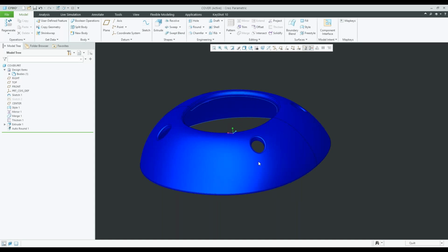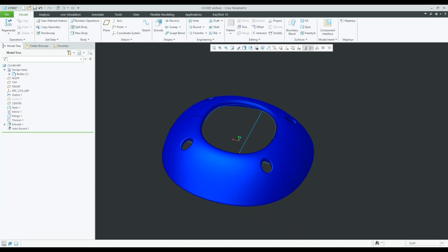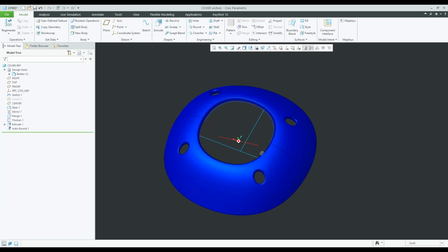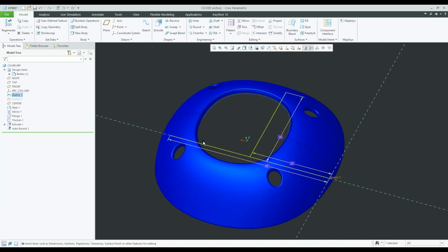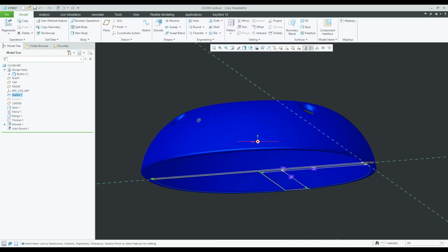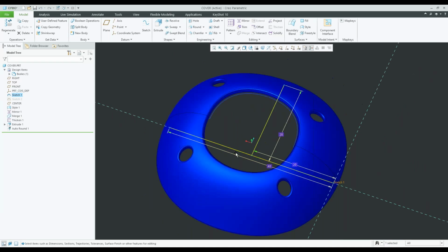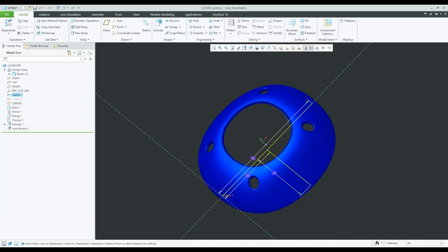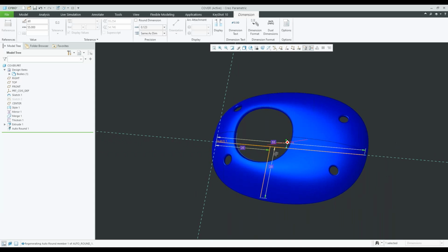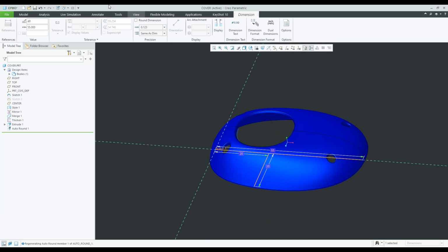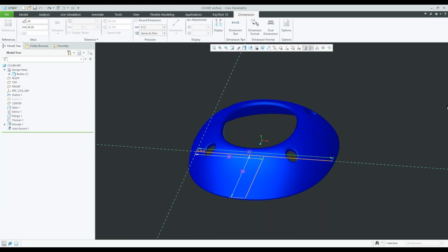There it is. Okay. So from here, though, we actually want to make some changes. Let's go back, and you can currently see that we have our surface created. I can come in here, I can grab sketch 1, for example, go into edit, and because those style curves or those ISDX curves are linked to the sketch that was created, I can change these dimensions, right, from 40 to 55, for example, right, and that's going to update and change and scale the way that we want it, which is good. I'm going to undo that for now.